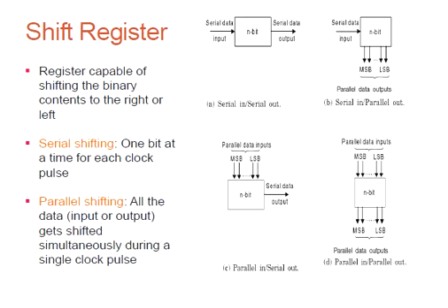There are four types of shift registers, where the first is called serial input, serial output. Here serial data is input into the device one bit at a time for each clock pulse, and the output also is taken in the same way. So output will be taken out of these registers as one bit of information at a time.